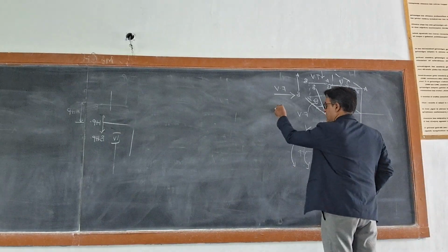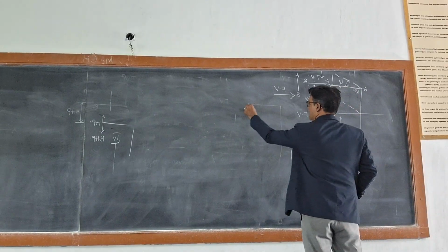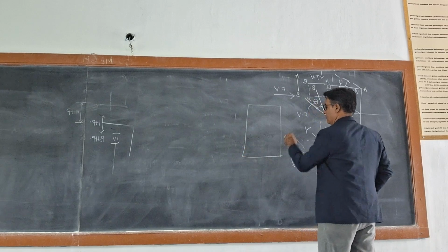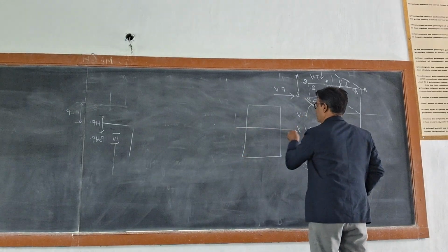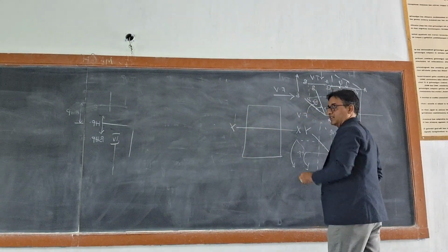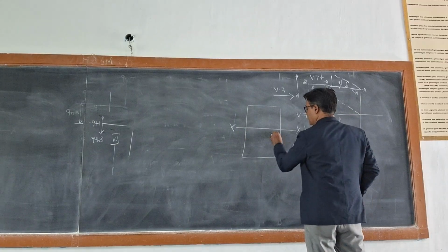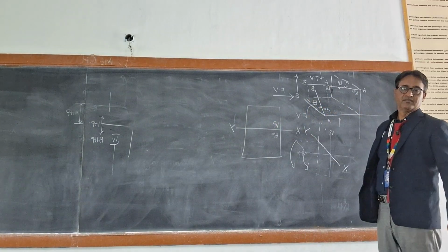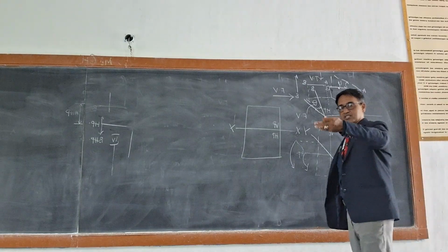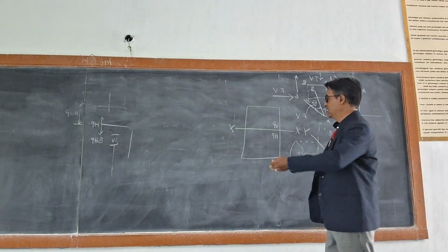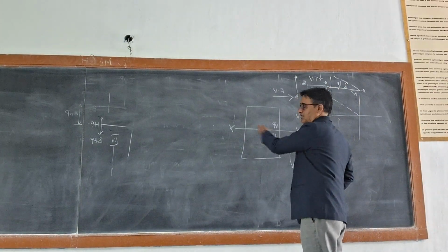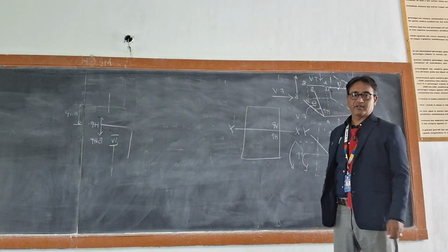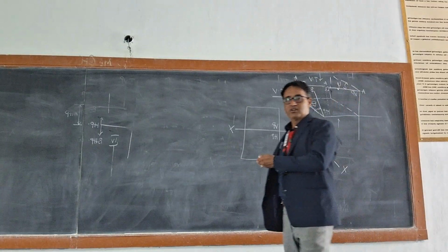So you will have the basic format, with a common reference line XY. Below XY will be your horizontal plane. Above XY will be your vertical plane. Okay, so whatever views or projections you are going to capture or generate will be portrayed on this particular format. So this is the first thing you have to understand.